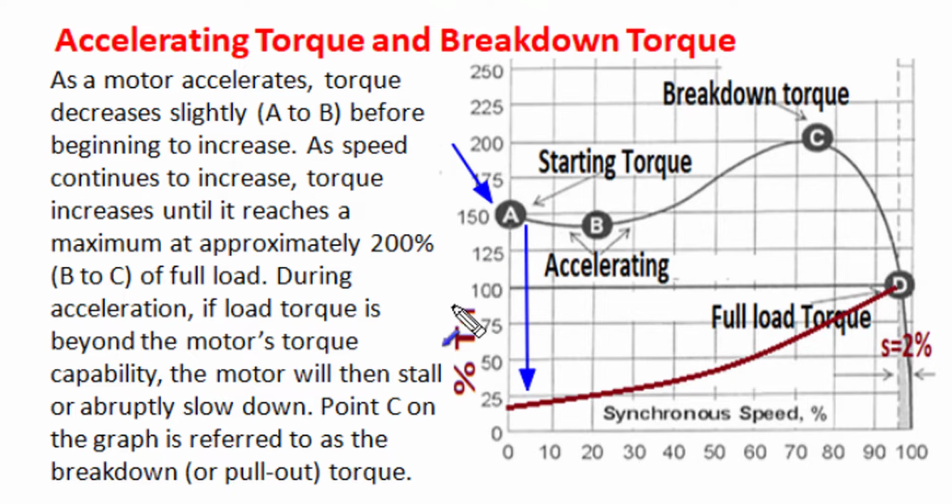Due to complex dynamic behavior, as motor attains speed, its starting current sharply decreases in magnitude, and at certain low speed operating condition, motoring torque initially decreases to a lowest value up to point B, where accelerating torque becomes minimum.